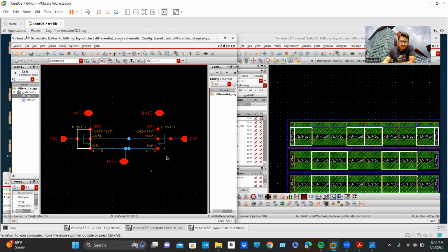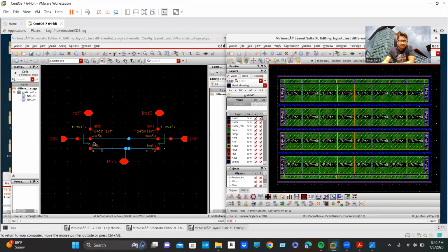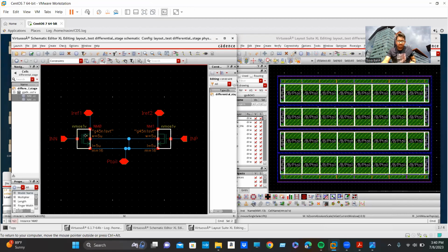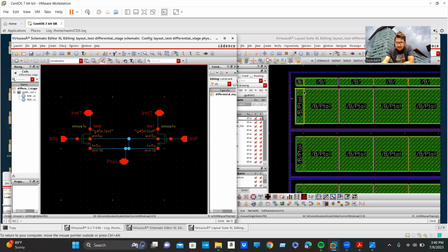demonstrated in my first video, and it is the differential pair, and it is the matching of differential pair. Okay, you can see it is a common centroid type matching. And in my first video, I also explain why and how I do that. In this video, I will just show you how we use dummy. Okay, nothing else. Okay, as I told you, this is my active transistor in the corner side.